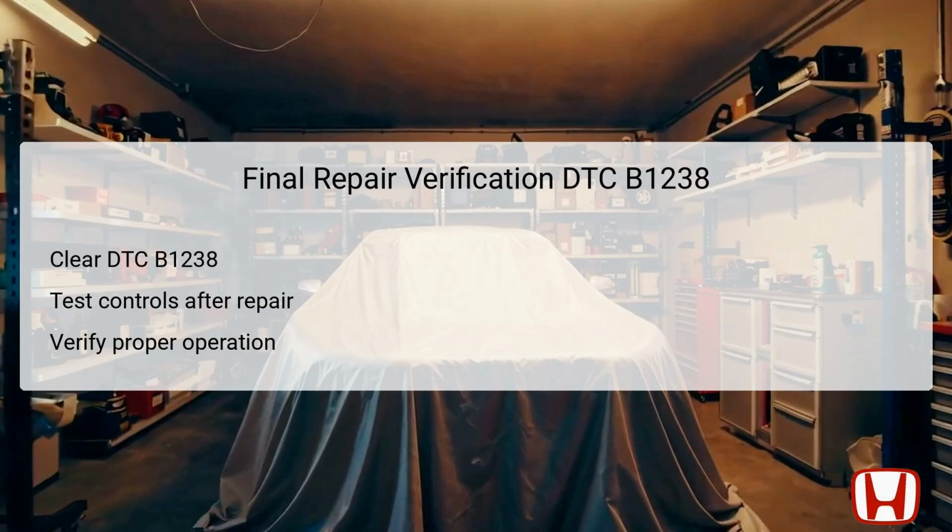After successfully repairing the identified components responsible for DTC B1238, the final verification step is crucial to ensure the repair was effective. First, you need to clear the DTC using the HDS or the climate control unit's diagnostic functions. After clearing the code, it is essential to run the climate control system to test the functionality of the repaired or replaced parts. Monitor the system for responsiveness, particularly focusing on temperature adjustments and airflow capabilities.